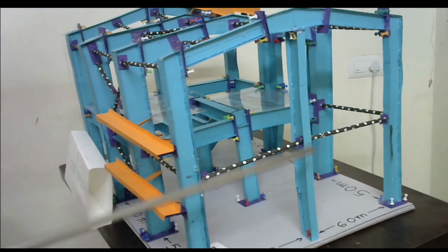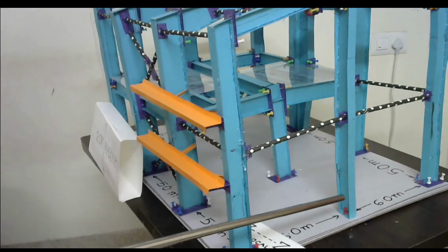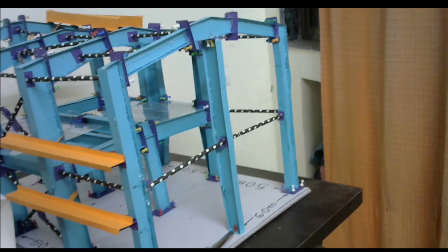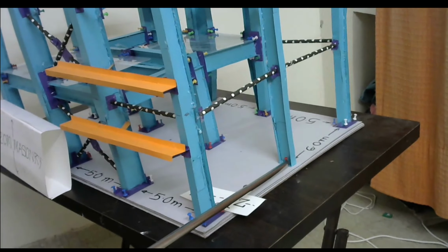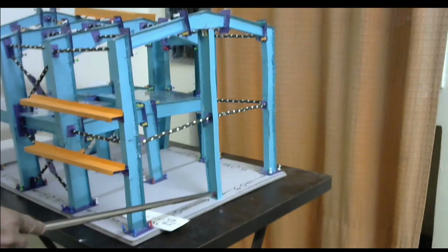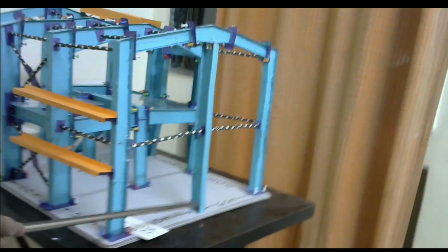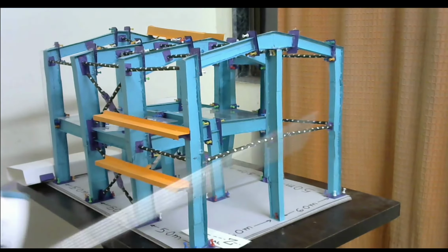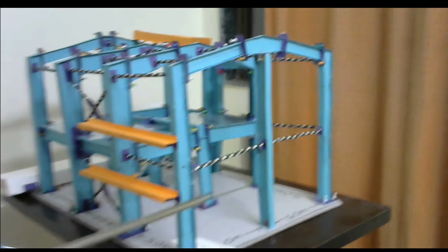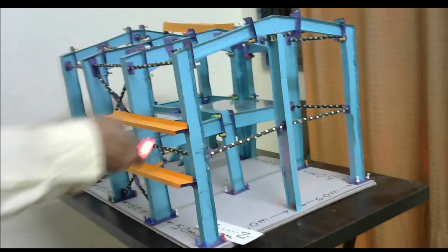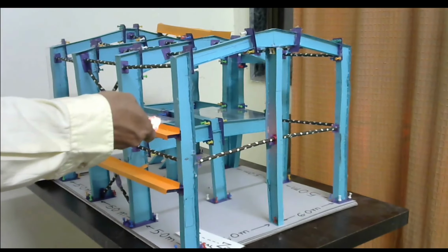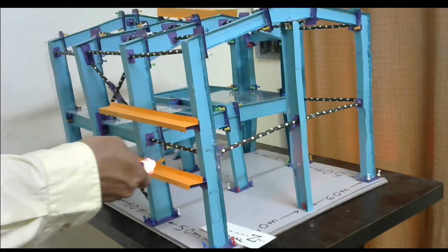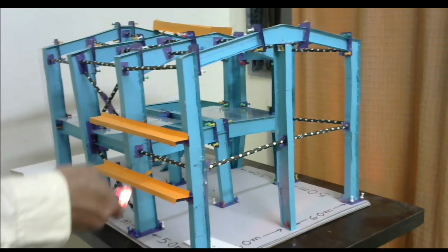Now these are the columns which need special consideration. Now look at this column. This is pinned at the bottom about both directions. Pinned. Now this column, for LX, if you see here, these studs are provided with end plates. So these are providing restraint against twisting, but the flanges are not restrained. But we can always take 1L. So LX will be 3 meter.